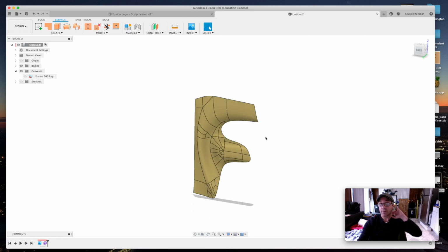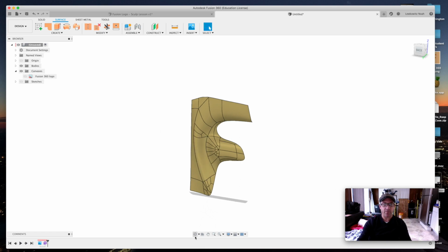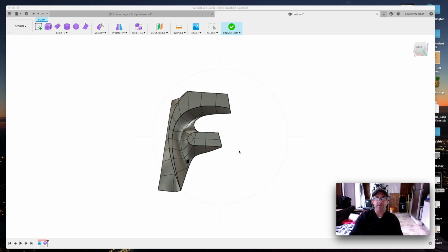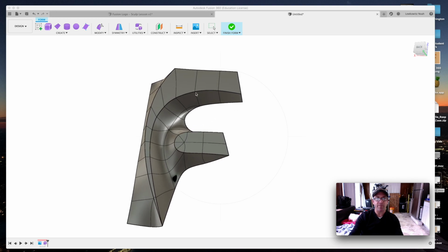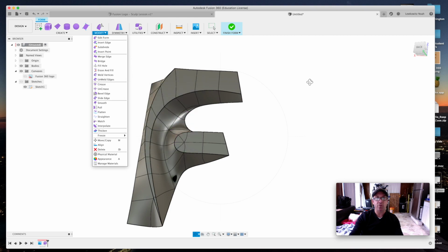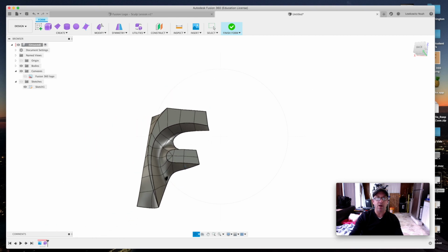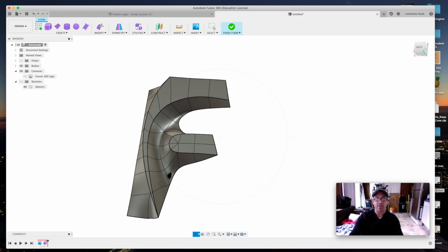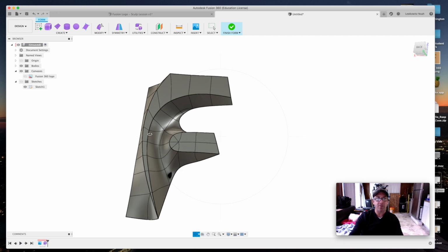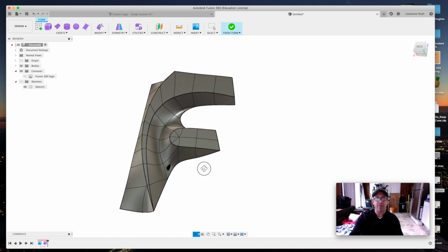And there it is. The next thing I'm going to do, just an insert here. I was able to fix my crease. I think it was this line or this line that wasn't being part of the crease. So I just went in and selected it manually and then went into the modify menu and chose crease. And that seemed to do the trick. So if yours didn't work properly or you couldn't get the whole line to crease, try doing that. And then you can go back and click on these lines and uncrease them, and everything should be good.